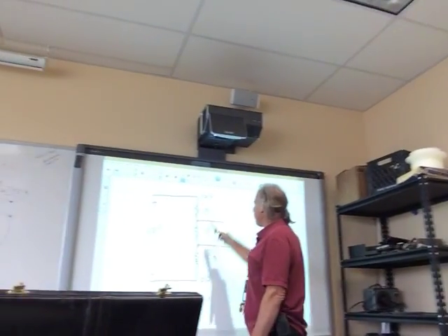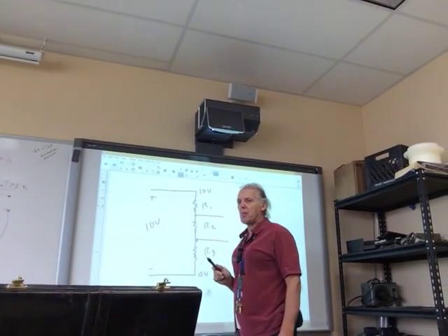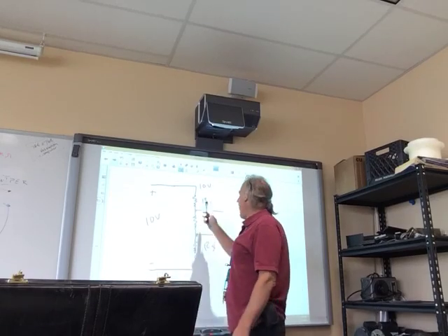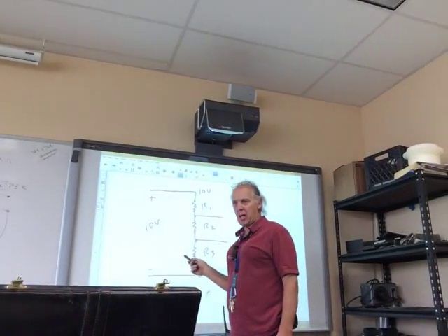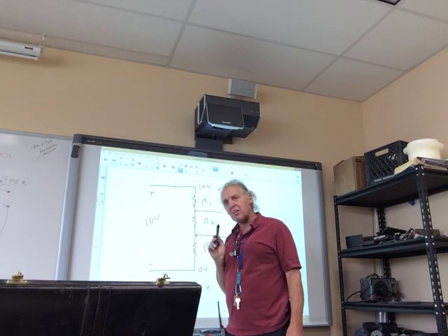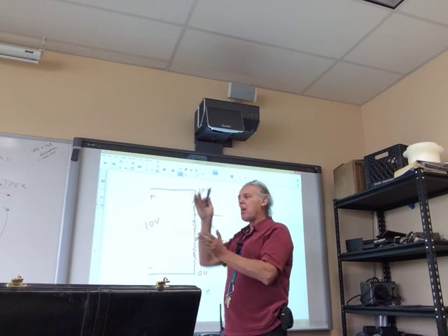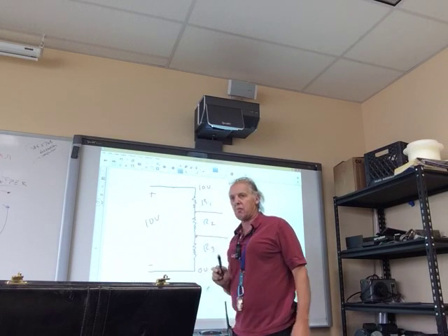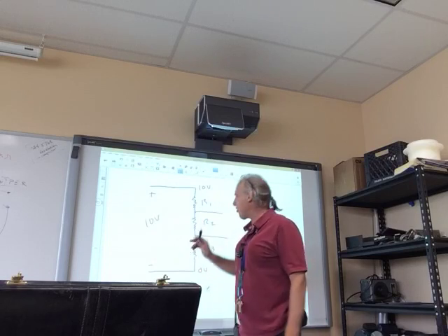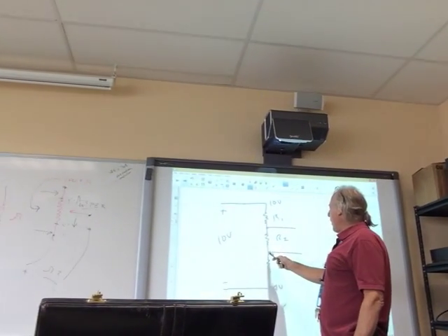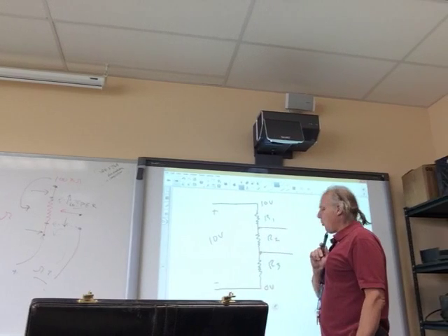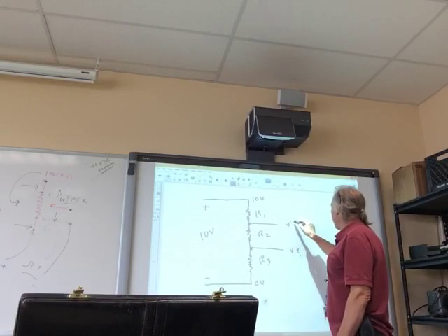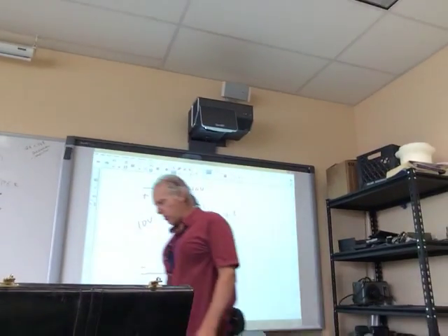So I pick resistors so that my supply will not end up burning up, because there's a certain current limit to my supply, and my resistors are a certain size so that current is not exceeded. I would like to find resistors that will add up and come out to whatever the current of the supply is, maybe a little less. At this point, I will have voltages at these 2 points here, and we don't know what they are yet, that I can use.